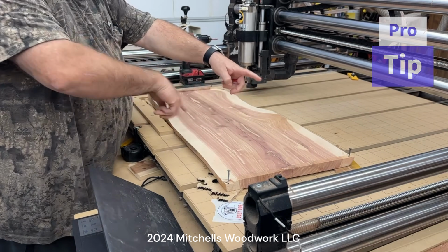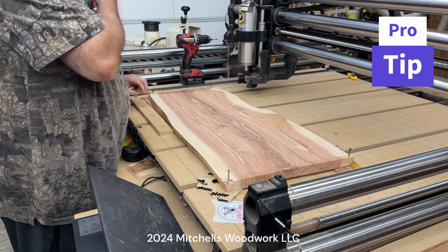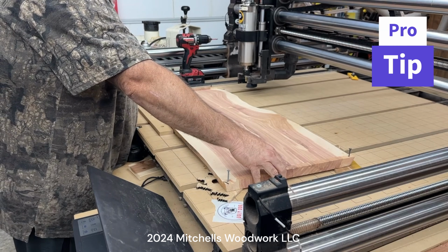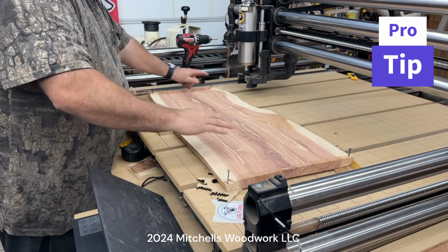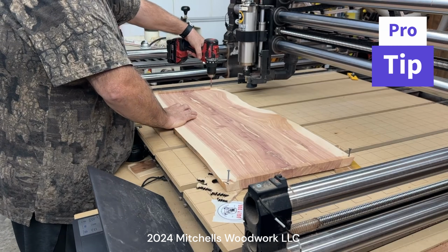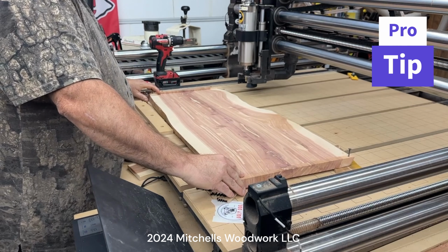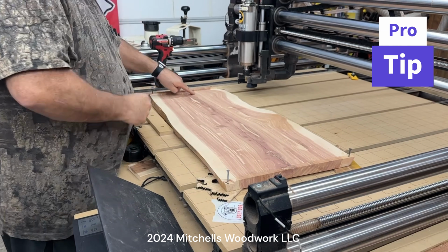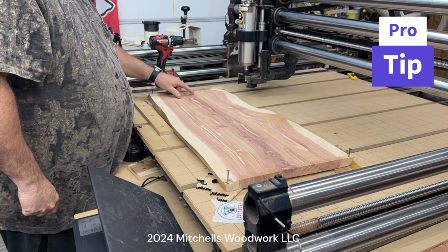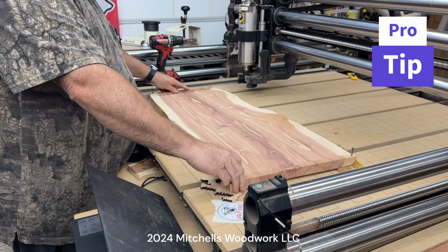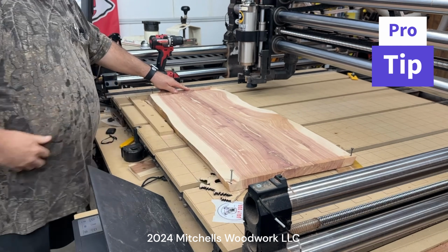All right, since there's no straight edges running a long ways here, I'm not going to be able to use my fence. So what I'm going to do, I'm going to screw this one screw down. All right, and then that'll allow this to pivot. And the goal is, I've got a pencil line drawn right down the middle there. And I am going to set this angle to be exactly parallel with the x-axis. And let me show you how I'm going to do that.